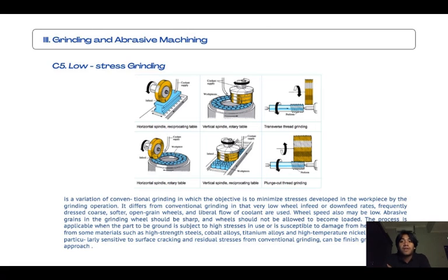And this rate is faster than those attainable with milling machines, even under the fastest metal removal conditions. Belts as wide as 10 feet allow the entire surface to be ground in one pass. The process can provide lower heat levels than grinding with an abrasive wheel because the belt carries away heat effectively.